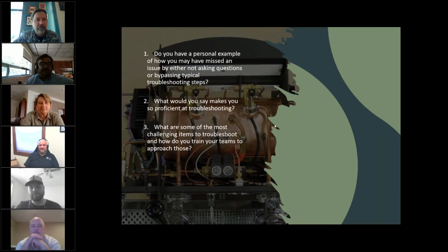Where if it's something built in the US, typically you're breaking the power side first. So that's my favorite one. I use that to tell my guys, make sure you know what you're working on. Make sure you know which side of the voltage line is being broken.